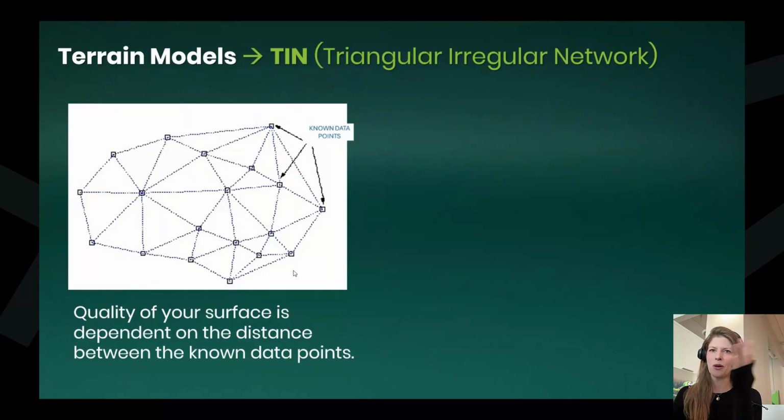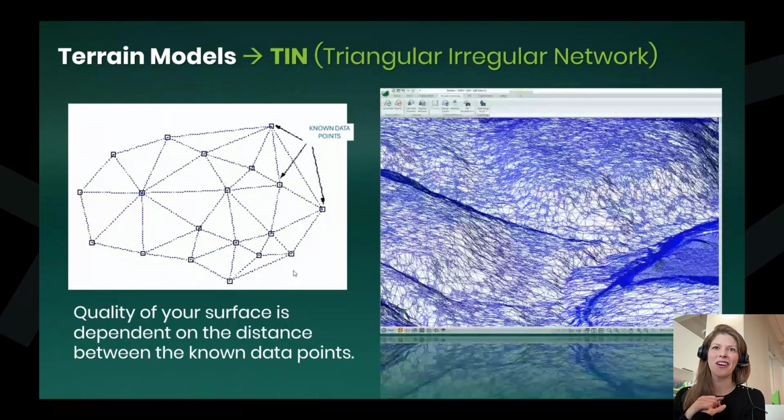And of course, we'll have a nice slide that gives us a good example of this. But for SRTM data, you might be 50 meters apart in your points, and some UAV data is like 10 centimeters apart. And that quality difference is going to control how many triangles are created, how big your file is, and of course, how accurate your volumes are going to be based on the data that you've got. So here's an example of some medium quality LiDAR data, the triangles created between the points.